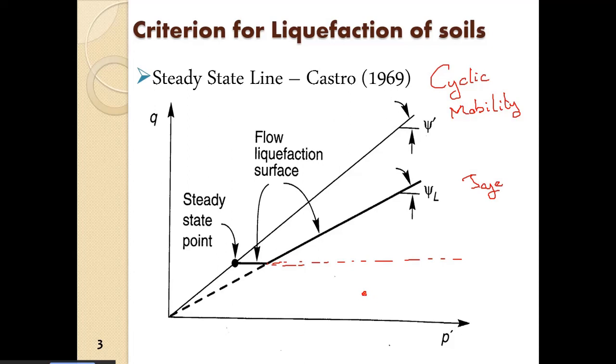So there will be stresses here, here, and there will be development of pore water pressure, and the stress path will move in this way, this way, this way, and it will reach this point, and it will oscillate on this failure surface, and the stress condition, all right, delta U will be 0, so stresses will be stabilized. So Q and P will only oscillate between this range.